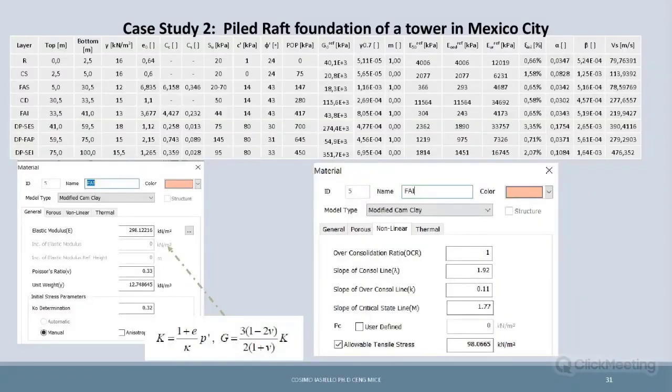So here, instead of using the soft soil model, what we used was the Cam Clay. The Cam Clay model, as you probably know, is the model developed by Wood at Imperial College London, and it is very useful when we want to capture the difference in plasticity or the yielding of the soil for overconsolidated clays. Cam Clay was basically developed for the London clay in London.